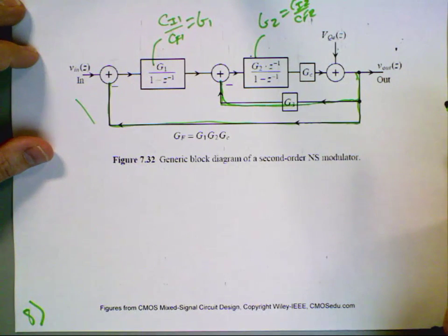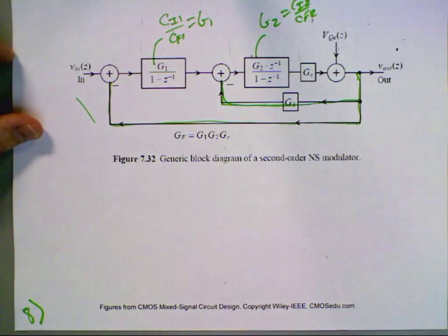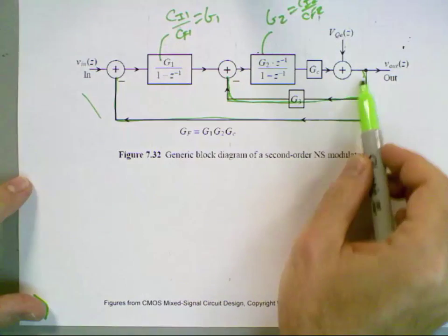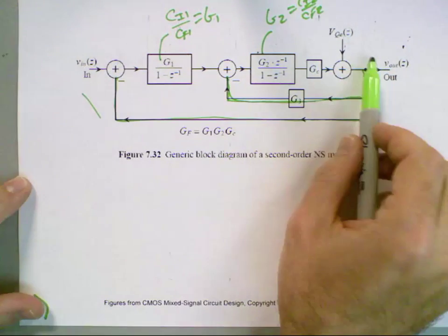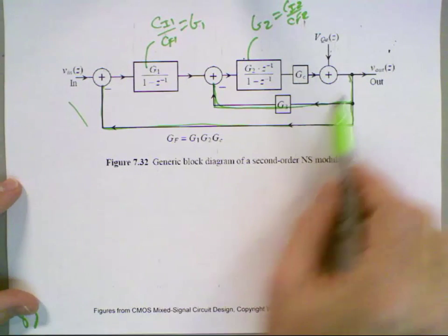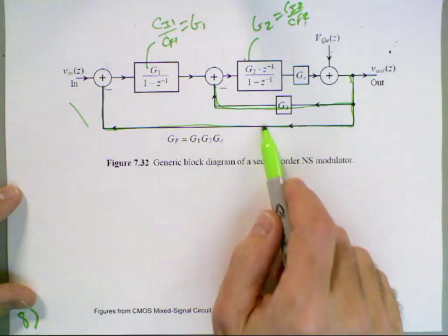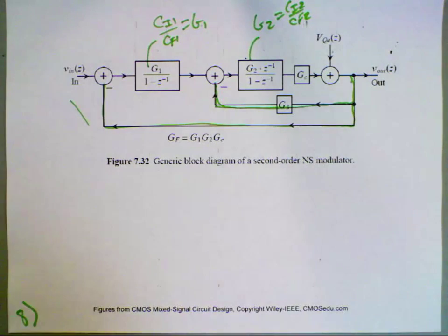Does everybody follow that? Simple example, if I have a speaker and I'm worried about instability, the further I take a microphone away from the speaker, the more likely it'll be stable and I won't have positive feedback and hear the screeching, right? Same thing here. The further I take my signal away from the output, the less likely I'm going to be unstable. This is the critical path. This is the one I need to focus on. Any questions about that? It's just saying, okay, I could put something here, but I'm not going to because it doesn't give me any more improvement.